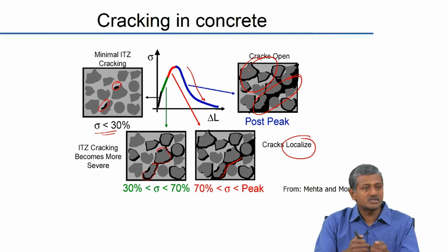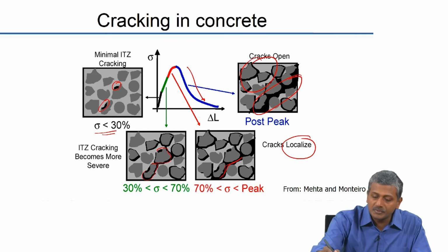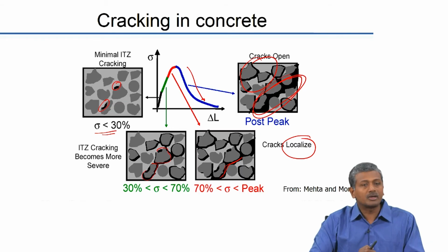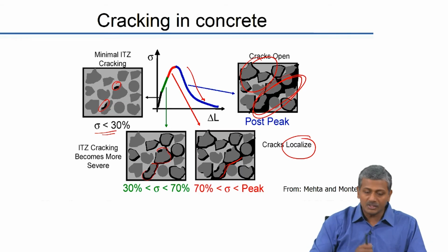Okay. But the stress relief here is not instantaneous, because this crack continues to open at a slow rate thanks to the interlocking that you get between the aggregates. So that is why you get this unique post peak behavior with concrete.